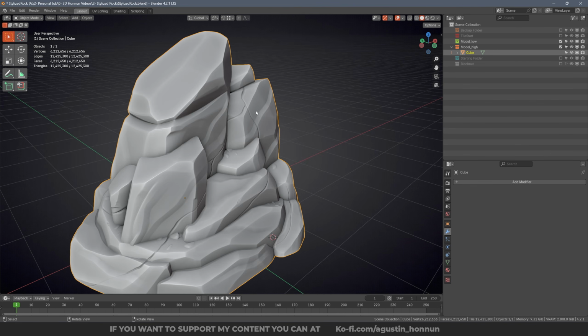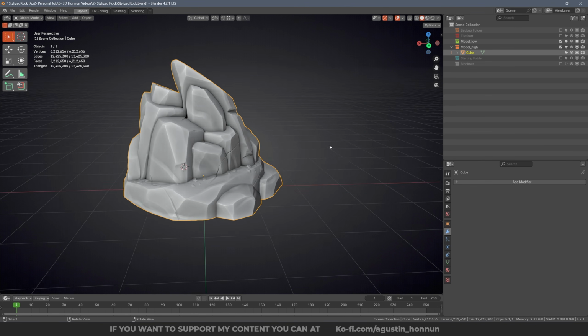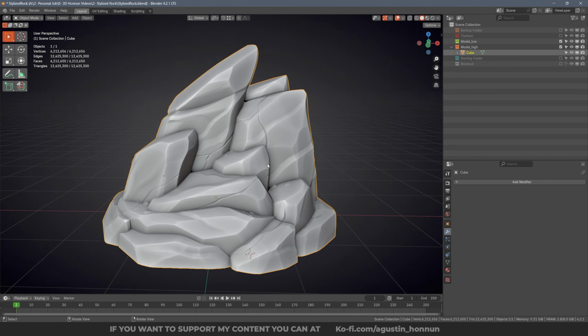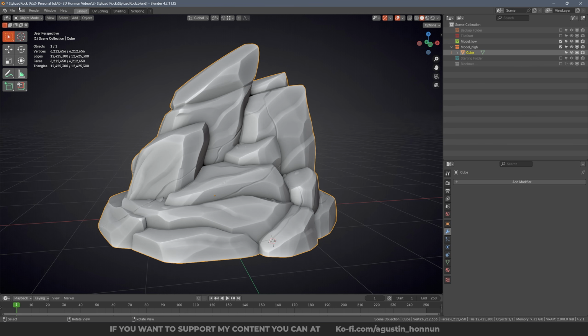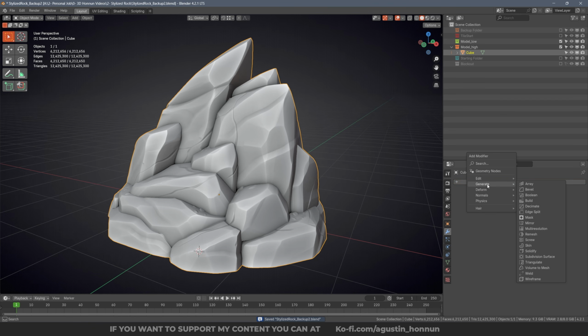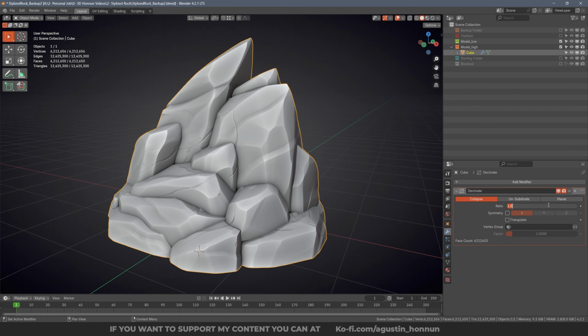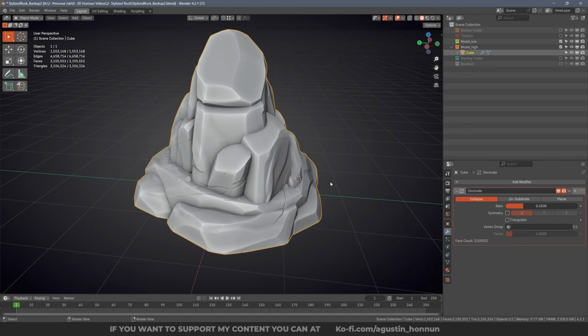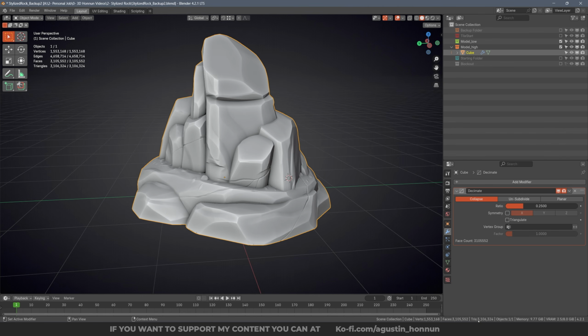So you can use this one as your high poly already, but if you have some crashes baking this entire model, you can optimize this a little bit. So I'm going to save a backup again. You can add a modifier here called decimate. And I'm going to be using a value of 0.25. That will take you some time. Alright, it finished. But we decreased from 12 million to 3.